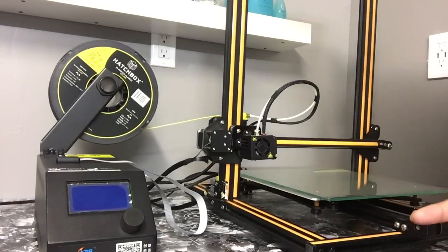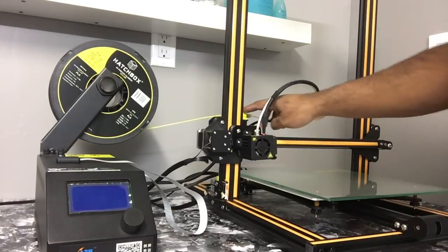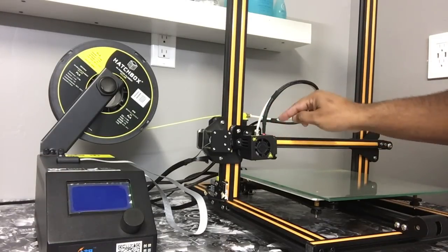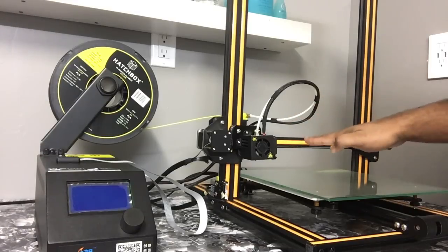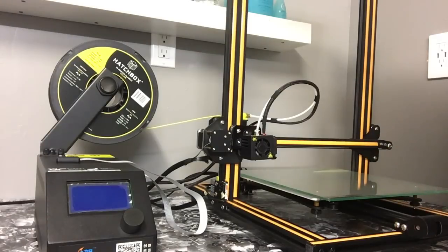Just be really careful on that, guys, because this Z-axis here, if you bump it, because it's all connected, it moves just a little bit up or down, and let's say you've printed about this high already, your nozzle is going to start here, so it's just going to knock over your print. So all the hours that you've spent doing the first layer or first height is going to go to waste. So just be really, really careful when you do that.